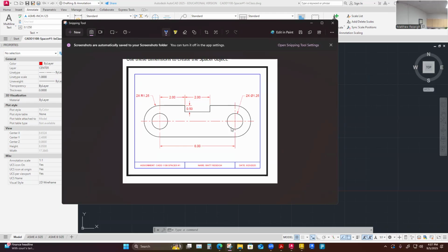The reason why I wouldn't do the circle, the hole, and just have that one center line, is because the circle and this radius share a center. They have a shared center. So if I'm dropping a center line here, I want to incorporate both features of this part, so I want to include the hole and the radius in marking a center of it.